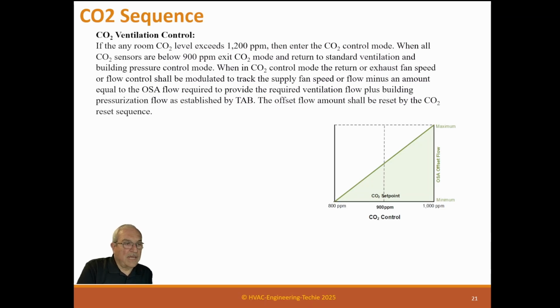So what's basically happening, you've got an air handler that's operating, maintaining building pressure, and if a high CO2 level begins, then we want to change that amount to greater. We're not going to change building pressure, but we want more air in between it, so we're going to exhaust some air now, or maybe even relieve a little bit of air to do that.